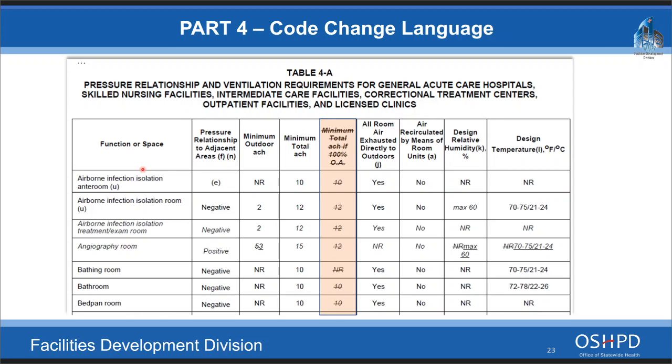I just got a call last night on a facility that was being changed into all administrative office space. Well, when we see something like that, we don't see an issue with plenum returns, things like that. But if you've got an operating room suite in there, then we do see an issue with it. So that's what we're doing at OSHPD in a nutshell in terms of mechanical. We're always willing to work with you and be flexible on that.